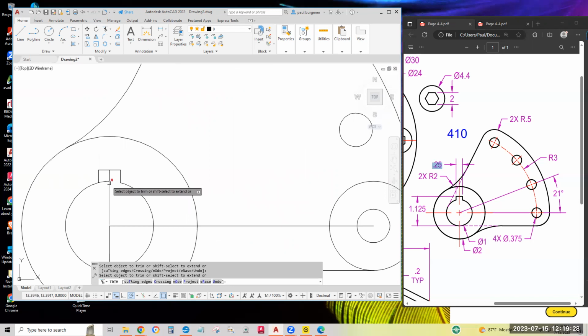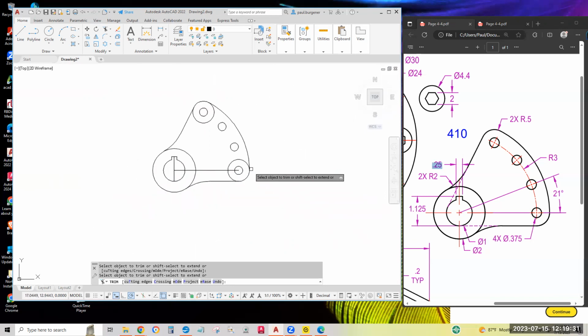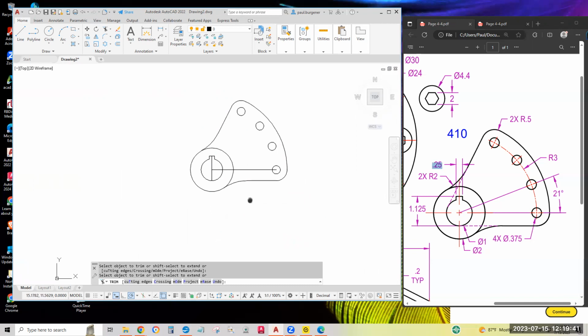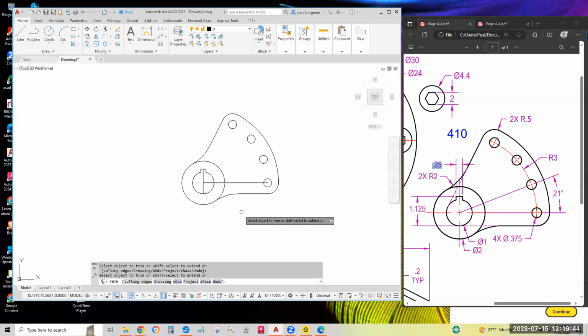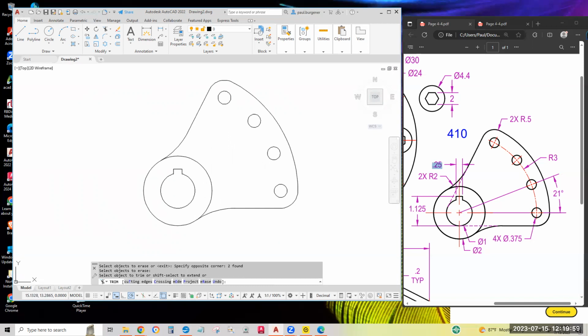And let's see, we got to trim those away and these away. Yep, and that away. All that's left is erasing these lines. Might be quicker if we finish the trim command, or better yet, invoke the erase option of the trim command. That way we can easily get the two lines without click, click, click, click, click, and all over the place, trimming tiny pieces away. Hit enter.